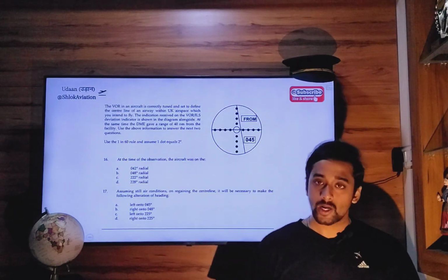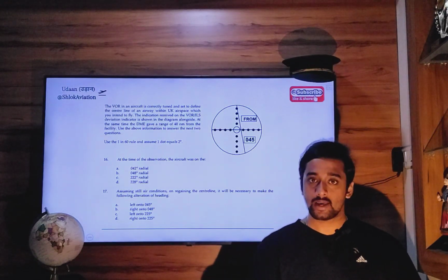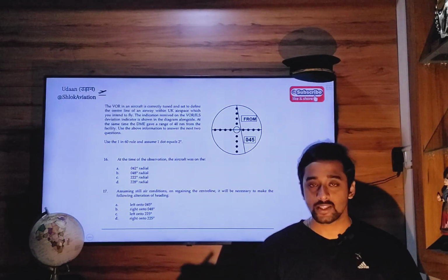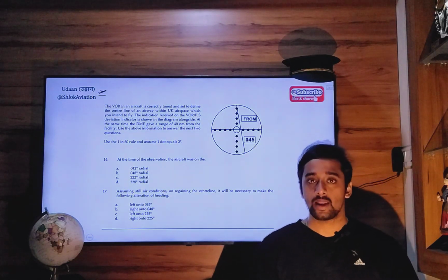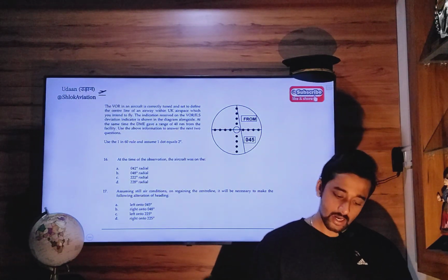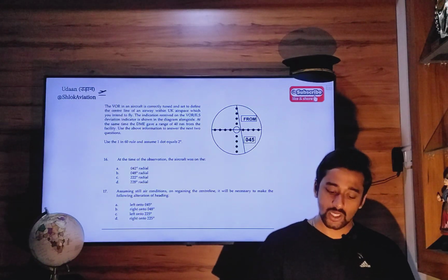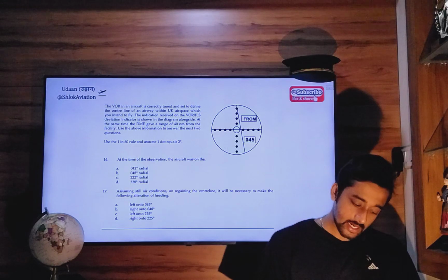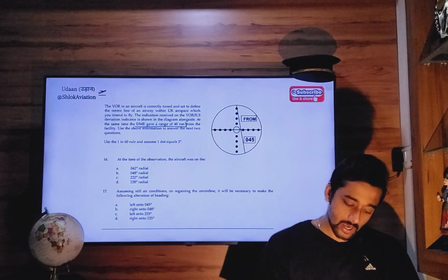Now, a very important practical question of VOR. By the way, I have also solved and answered all VOR based questions from Keith Williams, the Oxford book, and RK Bali, and uploaded them to my channel, so do watch that. Now here we have been given an OBS selector set to 045. We get a from indication. The DME is telling us a distance of 40 nautical miles.